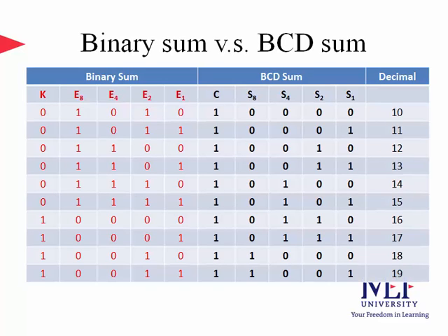So more explicitly, I've drawn a table. This table shows the binary sequences that differ for the binary sum and BCD sum. The decimal number representations from 0 to 9 are common to both sums because each is a single decimal digit and their representations are exactly identical. No conversion is needed for them.